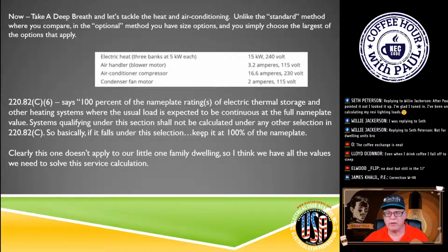And then, of course, this one here is with the electric thermal storage. Again, we would take the full nameplate value for that. So you keep it at 100% of the nameplate value. Clearly, if you have one of these electric thermal storage units, then you'll know, just take the nameplate value from it, and that's what you're going to add for your contribution, and obviously compare that to your AC or that type of thing. And so whichever's larger is the one you're going to go with.